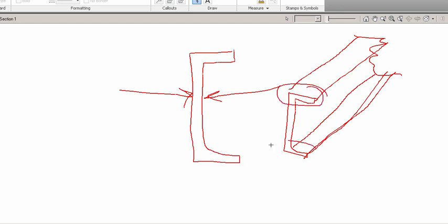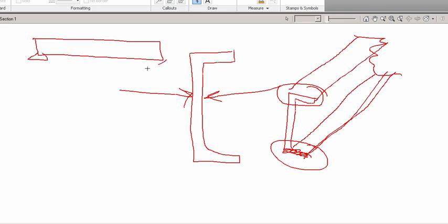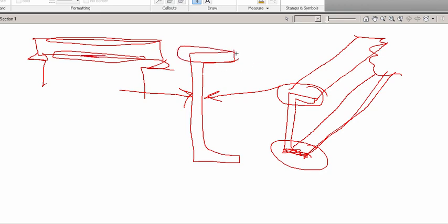Again, you'll notice that beams like this are also stressed in the same way. This is where the stress will be if it's actually spanning over a distance, like so. So the stress, again, is always in the top flanges, not always, but in most bending cases, the stress critical areas are right in the top, so therefore there's material up here and down here, and a thin web in the middle. This is still called the flange. They do call it like a toe flange, but it's still just the flange. This is still called the web. And of course, your flange width is this value here.